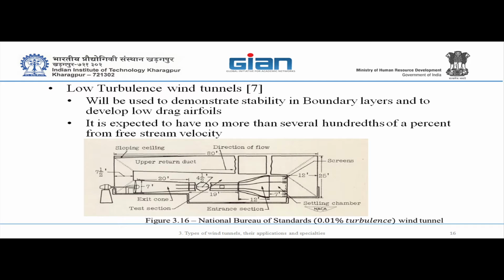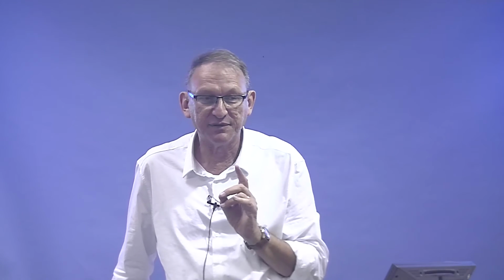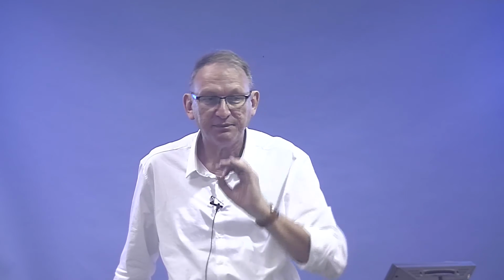2300. Okay, this is the transition number for pipe flow, but it's necessary, but it's not sufficient. You can run in a pipe laminar up to 100,000 Reynolds if the flow is very quiet, and you need disturbances to blow up turbulence.